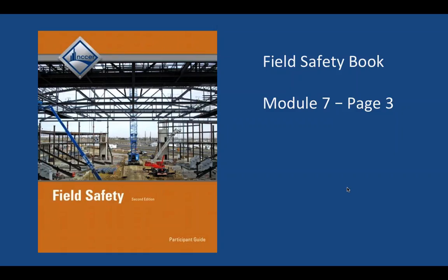So while performing maintenance on equipment, these are certain things we want to keep in mind. We want to make sure that we disconnect the power and then lock out and tag out any machines before we perform any maintenance. So before any employee gets their hands or any body parts into that piece of equipment, we want to make sure that we're locking out and tagging out. At a minimum, taking that key, grabbing custody, tagging it out, and making sure that there's no other key in circulation. In addition, we may have to block hydraulic arms or lifts if they're in a position where they may possibly harm an employee.